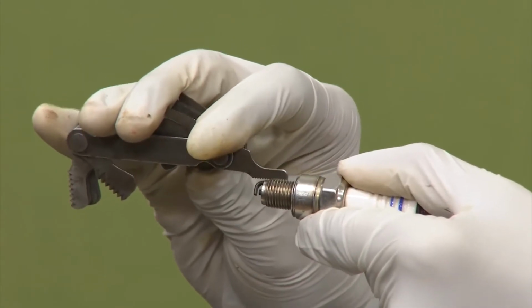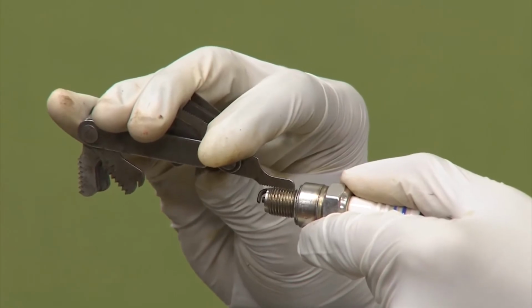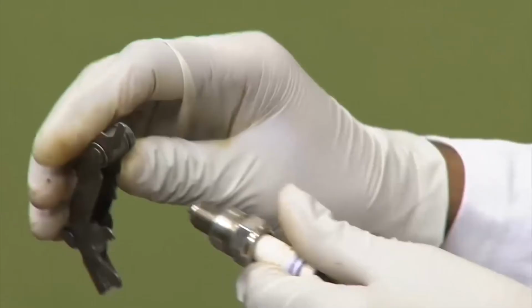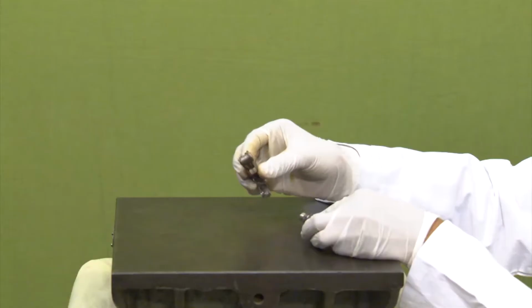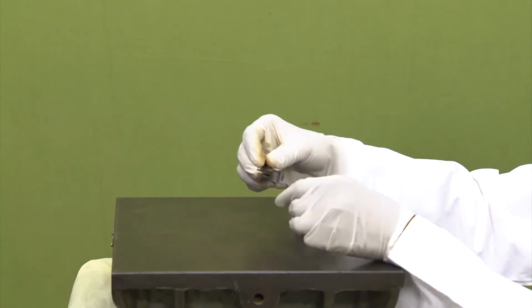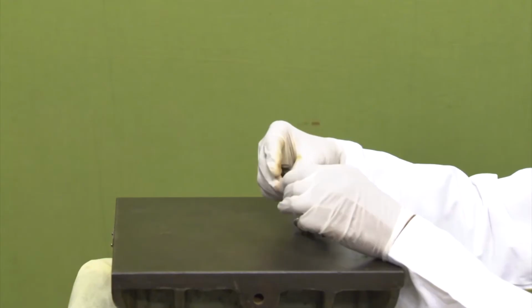You can see the 0.9 mm is a little smaller. So 1 mm is the proper pitch here. So the thread gauge is also sometimes known as screw gauge. It is also known as pitch gauge. It is used to measure the pitch or lead of any screw thread.